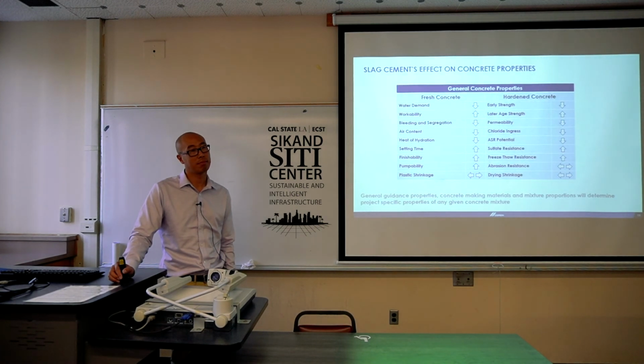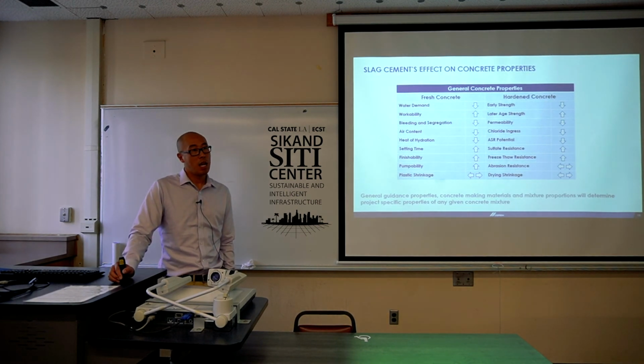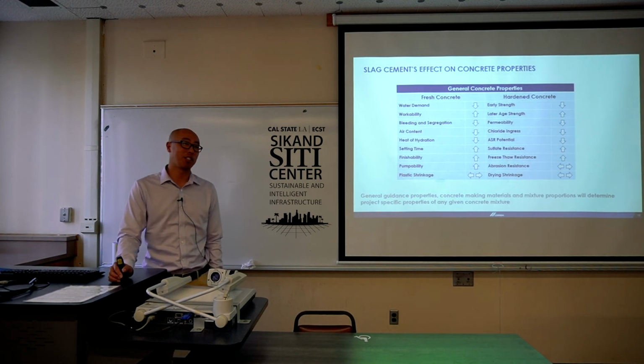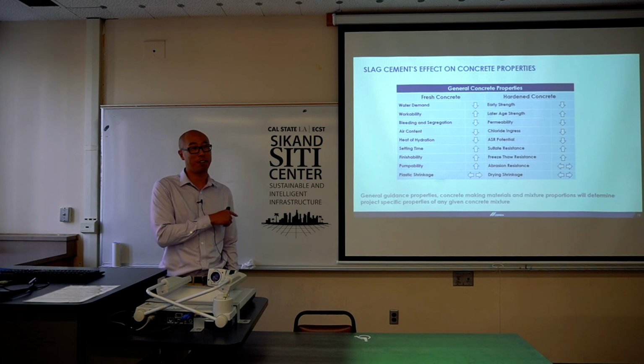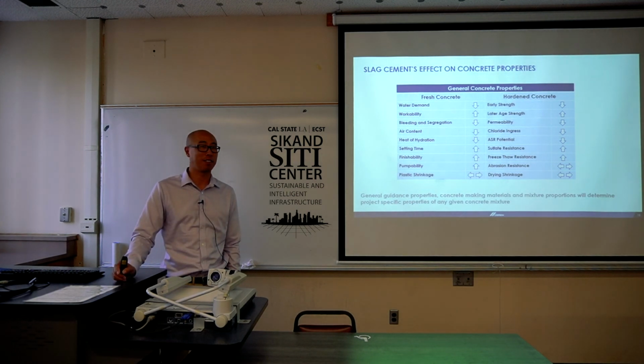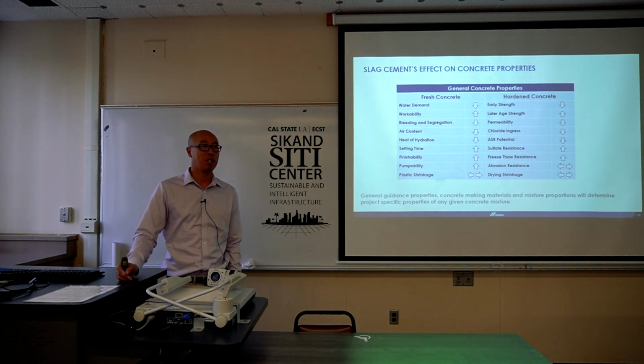What about pavement applications? So this is a pavement class, and I guess. Yeah, for pavement applications, one of the good things about using slag, as I mentioned, is that it increases durability. It's going to make your concrete very easy to finish. You're going to increase the uniformity from batch to batch.